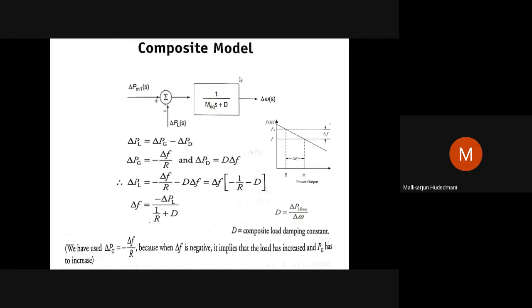As the load on that generator keeps changing, the frequency falls. Then the governor, if it is set to command, will change the set point in proportion to the drop in frequency. Then the droop nature of the generator becomes an important thing to visualize.